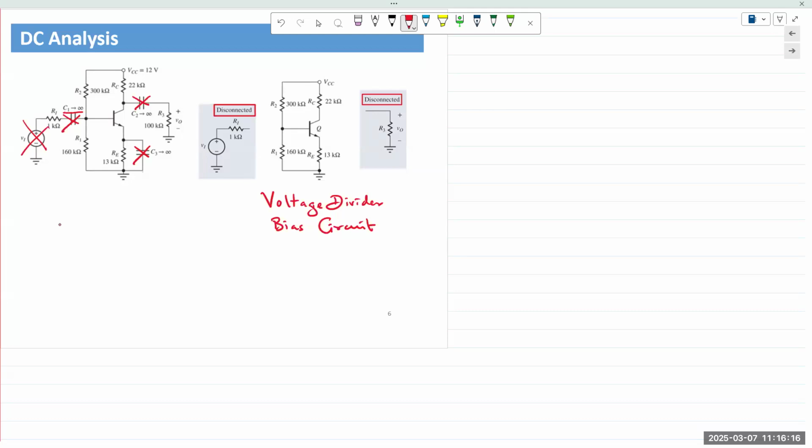They have to move a lot of mass, meaning there's a big cone that needs to be moved. That requires a lot of power. That's one of the things. But the frequencies that go to the subwoofer are typically less than 150 hertz. So that's where a low frequency amplifier is used. And it's a complicated design. So that's one of the reasons why good subwoofers cost a lot of money.